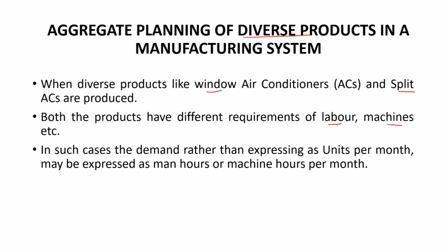In such cases, demand, rather than being expressed as units per month, has to be expressed in terms of manpower or machine hours per month. We cannot use units per month because different types of products may require different manpower and different machines. So, we have to convert into a common input scale.